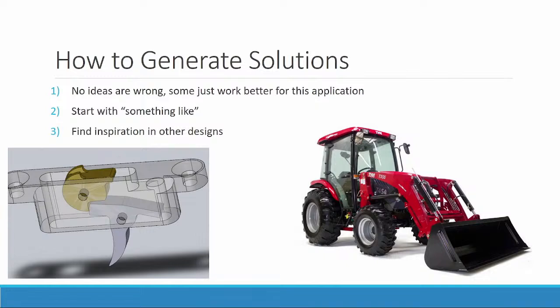Another idea that was used on Queso for our launching mechanism for our drone to hold back all the force of our springs was a crossbow trigger mechanism. It ended up being probably the most simple mechanism so that all that force wasn't carried in the servo.